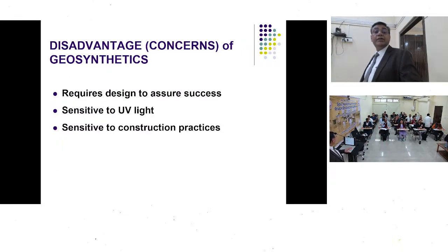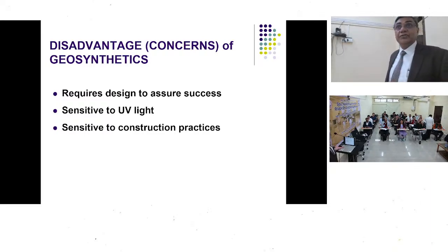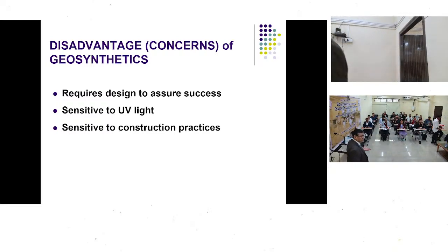But is it really that good? Or do we have disadvantages also? It does have disadvantages. Number one, it requires design to assure success. Suppose someone at a project is using a certain type of geotextile, then you at your project should not just copy him, stating that he is using it so I also use it. You have to see what forces are going to come at your project, what the application areas are, whether I can adopt his design as it is, or I need certain modifications. So it requires design to assure success.